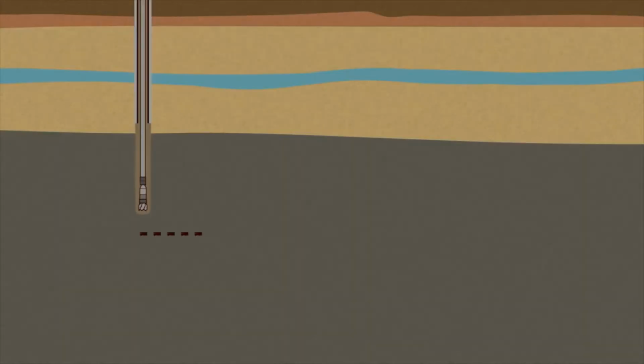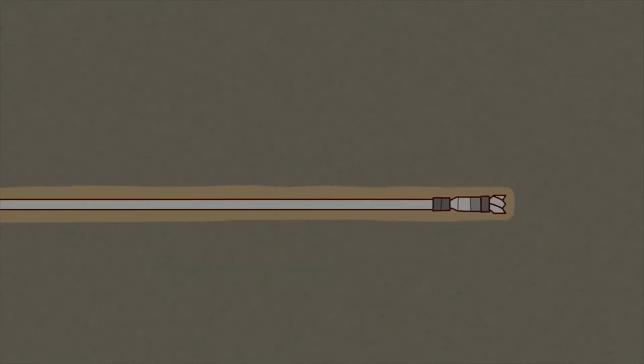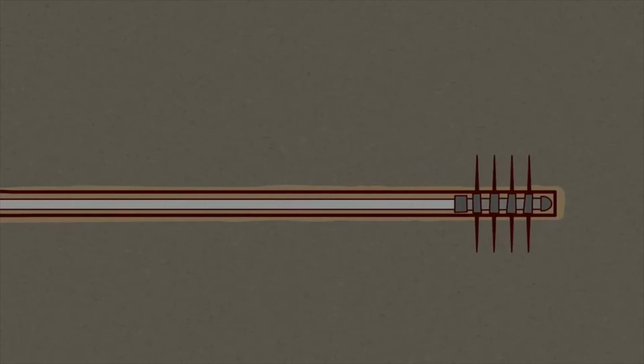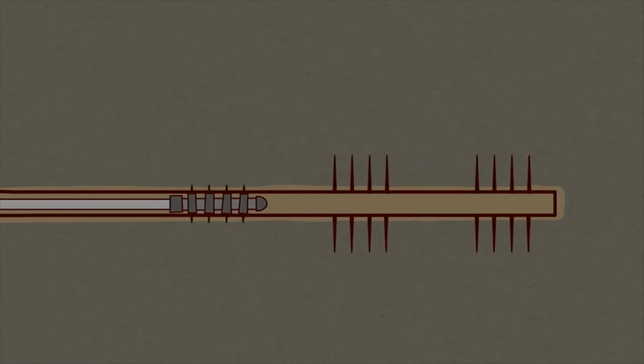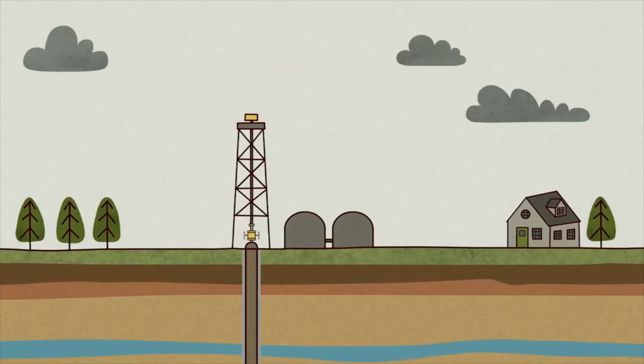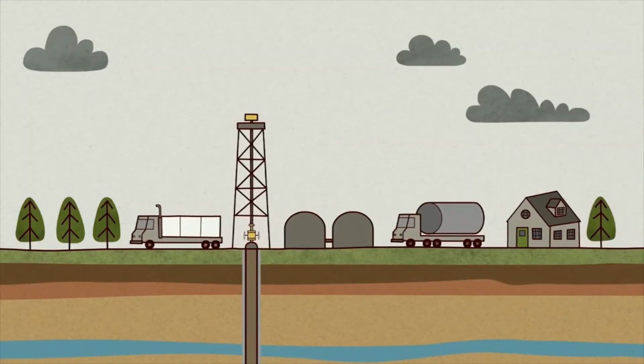When the well reaches 2,500 to 3,000 meters, it's at its kickoff point, where it can begin the process of horizontal drilling. It turns 90 degrees and extends horizontally for about 1.5 kilometers through a compressed black layer called the shale rock formation. A specialized perforating gun is then lowered and fired, creating a series of small inch-long holes that burst through the well's casing into the rock layer.